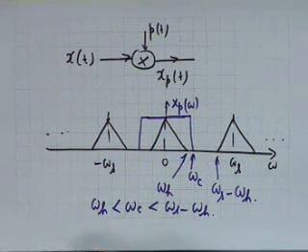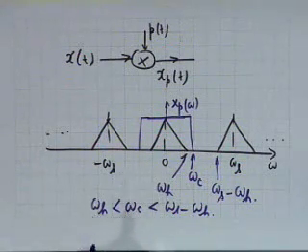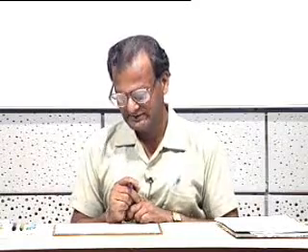So, in practice, there is an approximation to the ideal low pass filter also, and there can be a source of distortion. The sources of distortion in a practical sampled system can be three. Number one, ideal impulse sampling cannot be obtained, because an impulse cannot be realized in the laboratory. All you do is take narrow rectangular pulses.